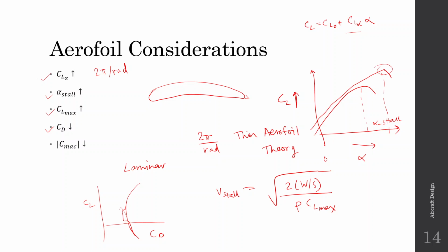So these are special low drag aerofoils, but the disadvantage is that these are difficult to manufacture and also difficult to maintain, because like we said, even an insect or dust particle or rain or snow might make the aerofoil shape ineffective. So these need high maintenance.